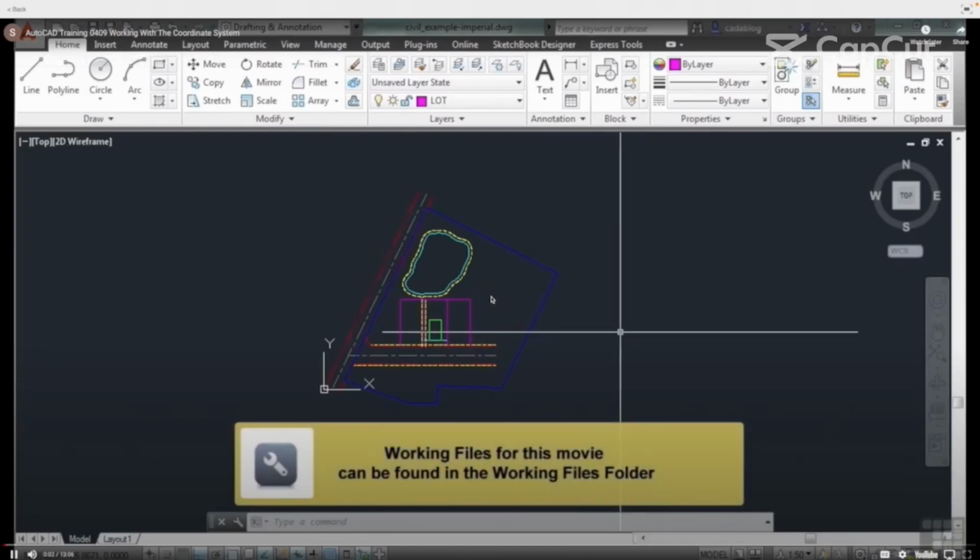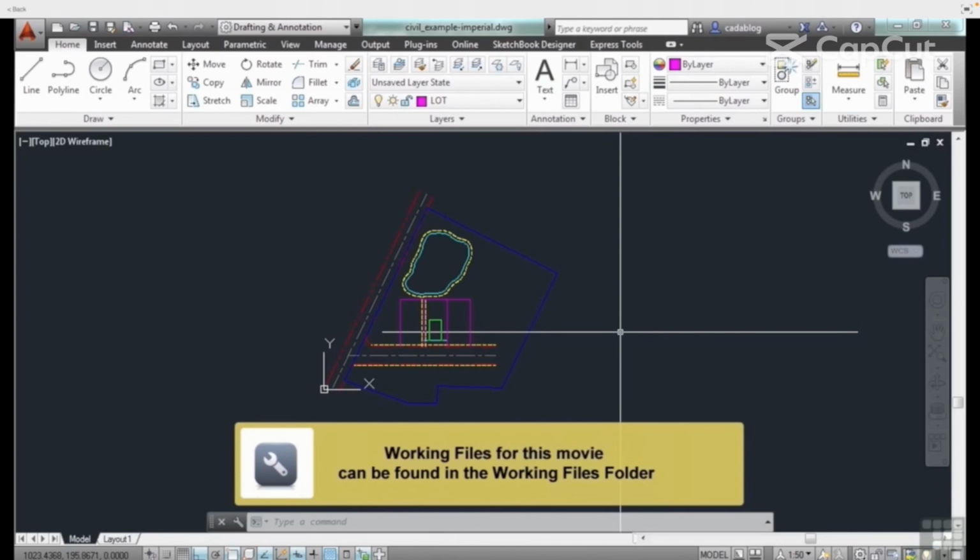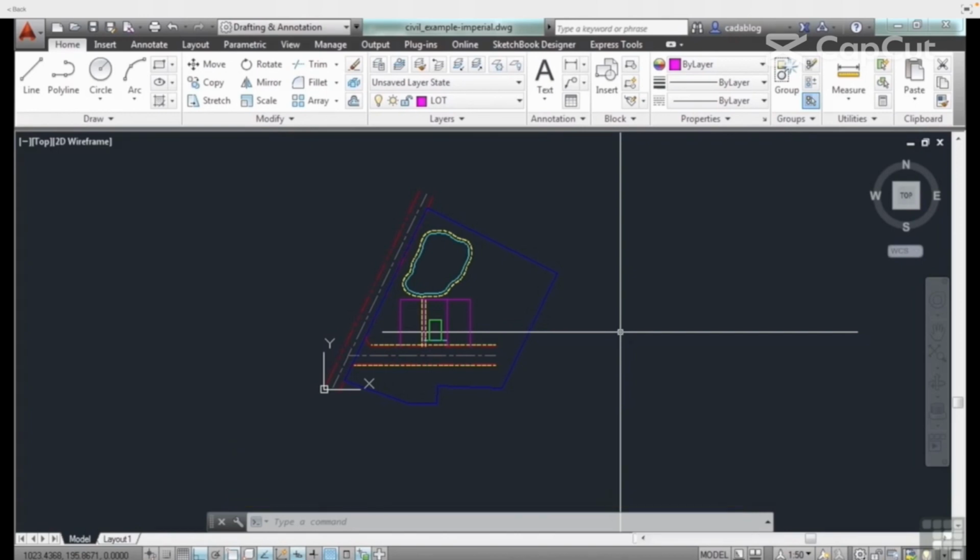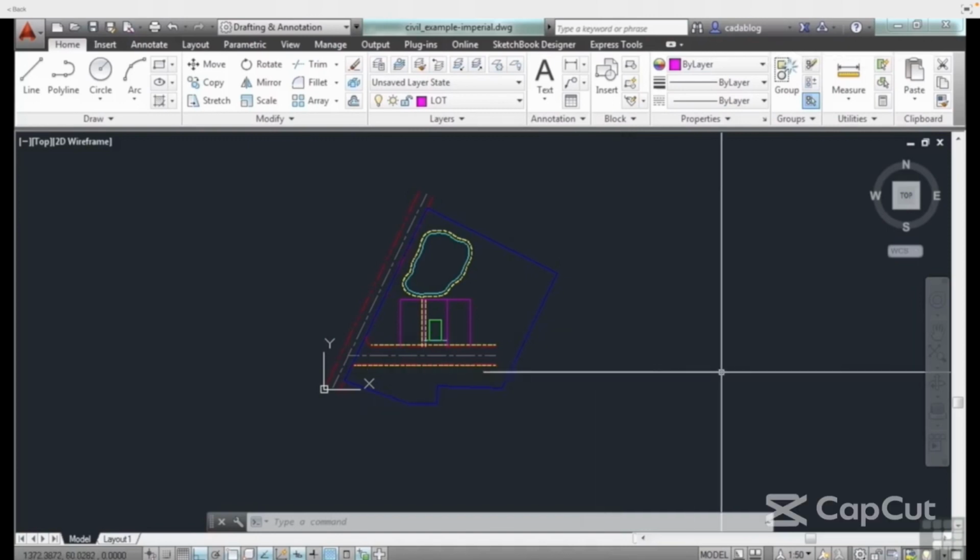By default, AutoCAD sets up the UCS in a world coordinate system. That means that the origin is at coordinates 0, 0, 0, a 0 for each axis. In AutoCAD LT, there are only two, X and Y. So it sets up the origin at those coordinates of 0, 0, and that angles facing east or to the right of your screen start at 0 degrees.